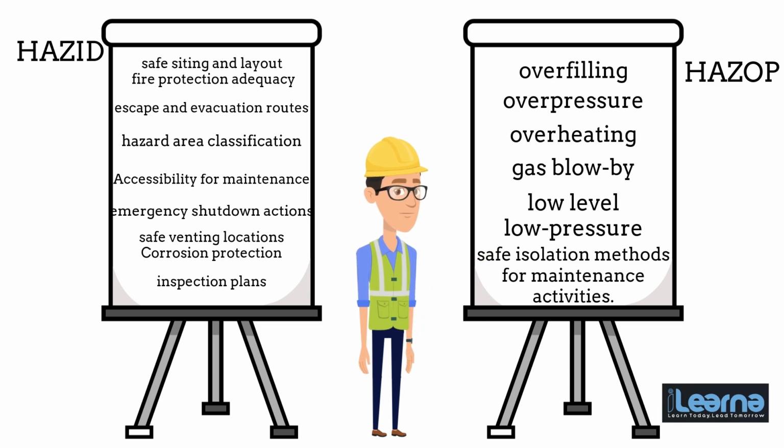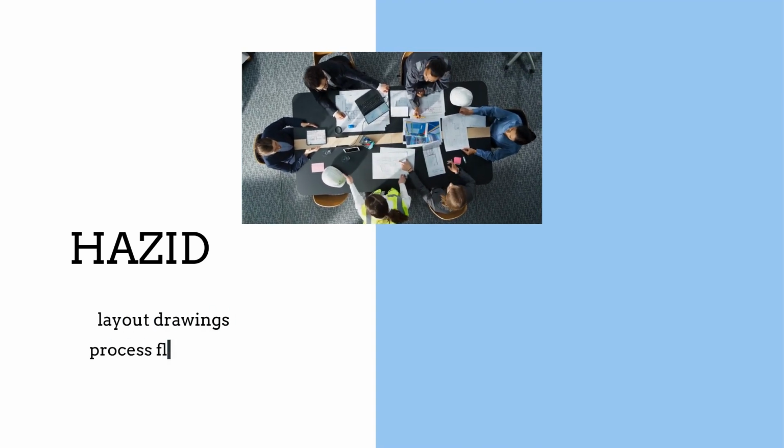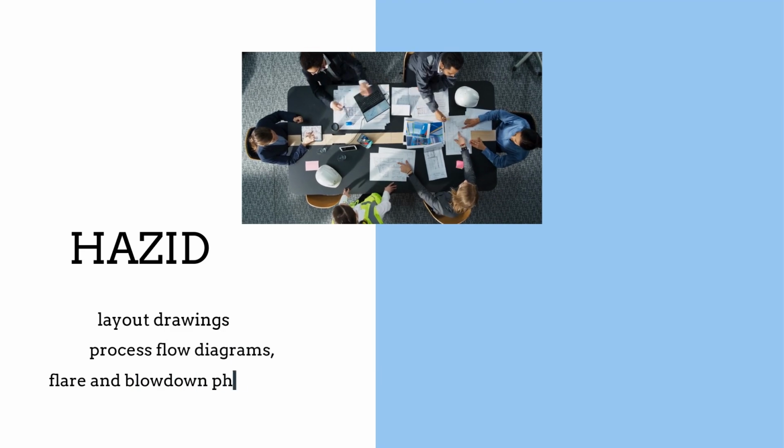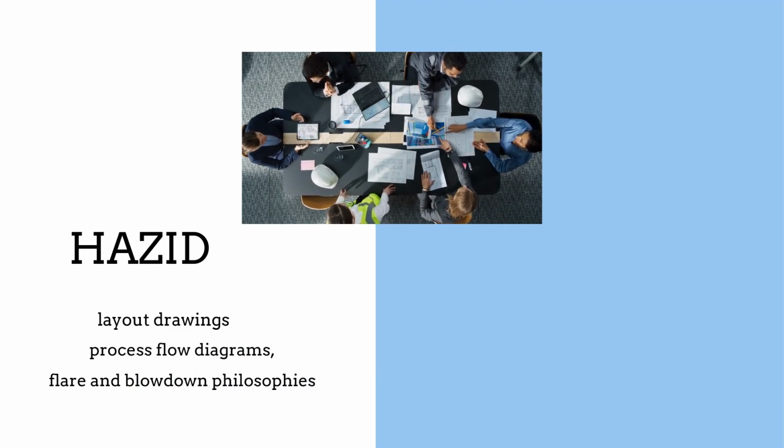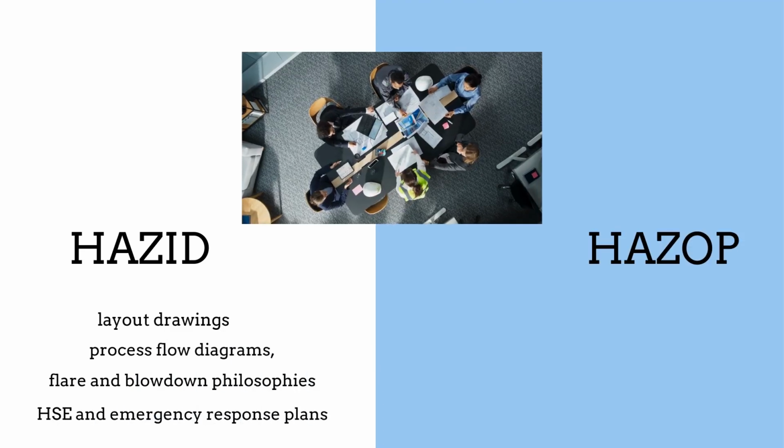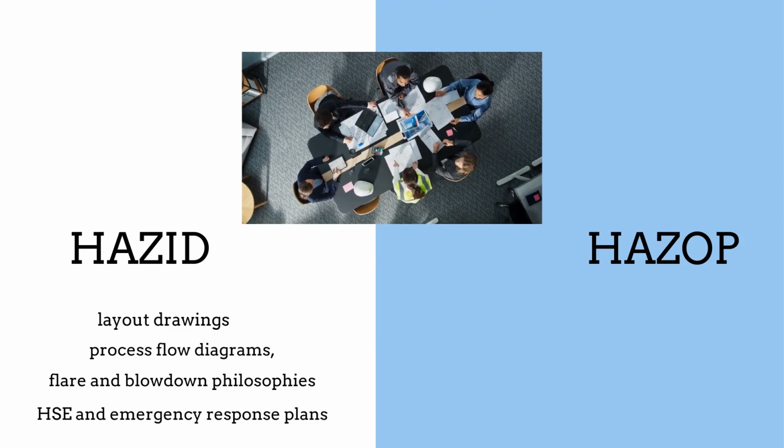Now, let's discuss when these studies are typically conducted. HAZID can be conducted at a very early stage of the project phase, once key documents such as layout drawings, process flow diagrams, flare and blowdown philosophies, and HSE and emergency response plans are ready.